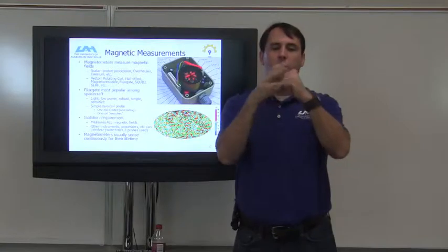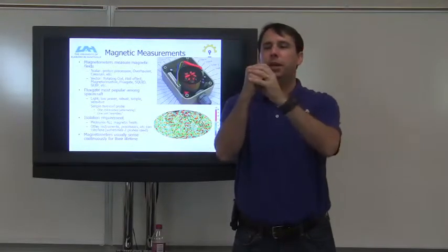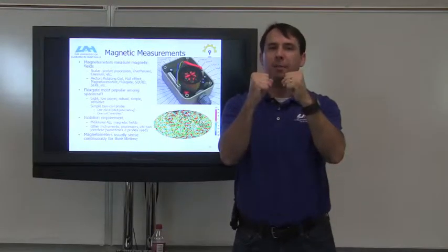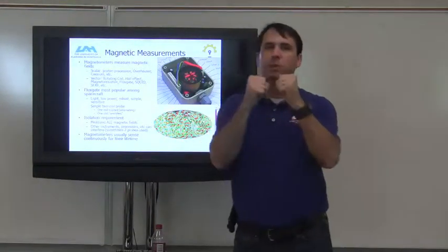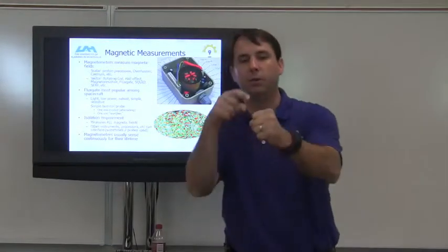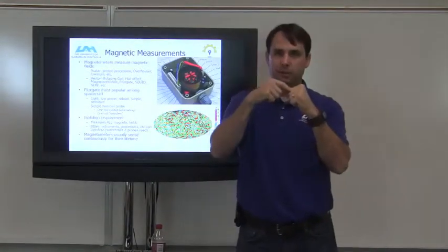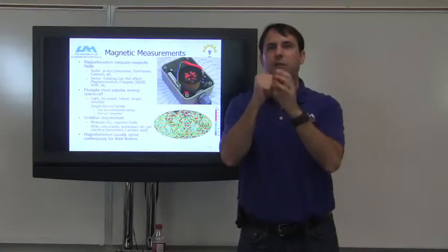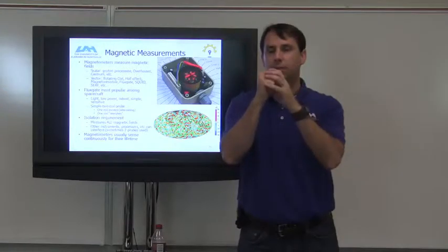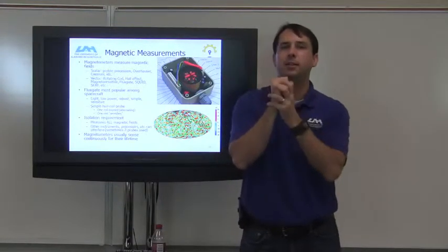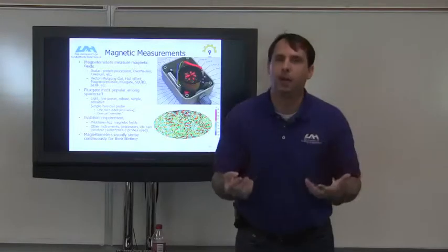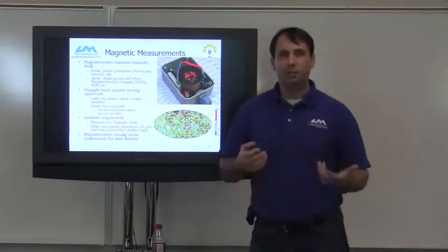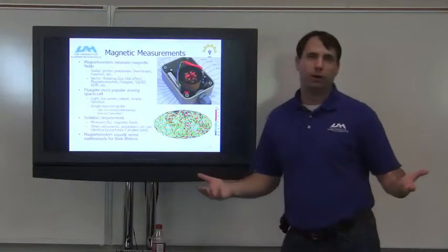So this magnetic field influences this coil of wire, but it's a known value. And so if you take this magnetometer, these two magnetic fields, and you put them in another magnetic field, the magnetic field that is set up by the magnetometer is changed. That change is felt by this coil over here that's just sensing. This sensing coil feels the change, and because they've calibrated it, it can tell how much of a magnetic field it just felt. That's how magnetometers work, essentially.